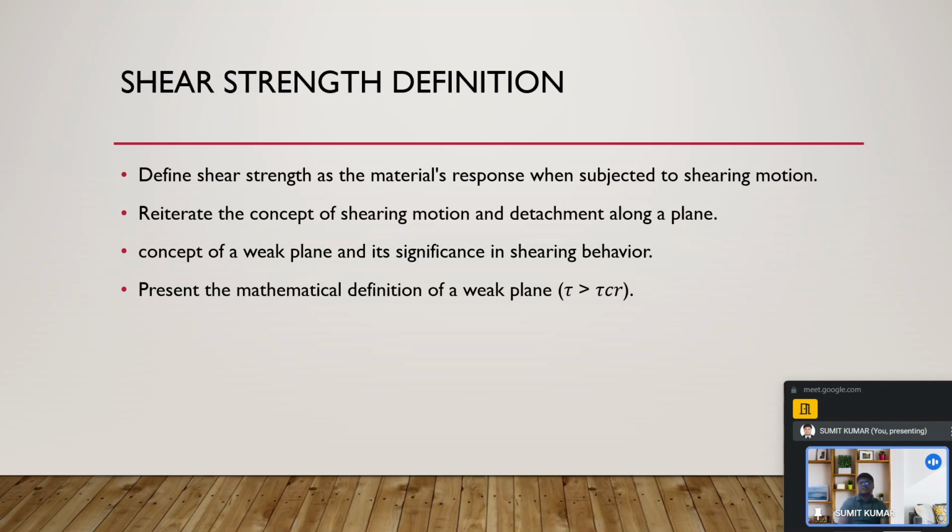When we talk about the concept of the weakest plane, it is the plane along which failure takes place. From there the soil cuts down and flows ahead. At that critical plane, when the applied stress is more than the shear strength at that section, it leads to the breakdown of the soil. So that is the weakest plane concept.